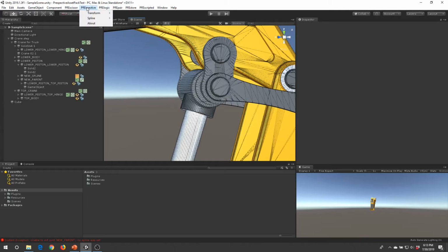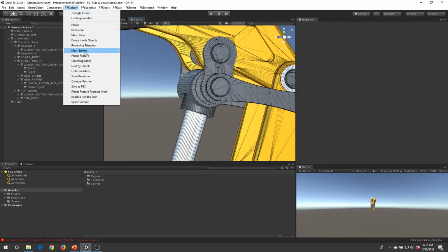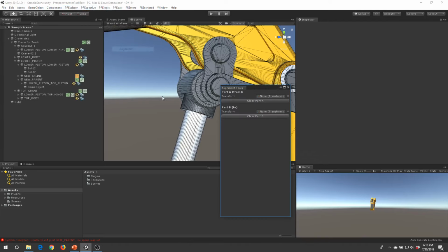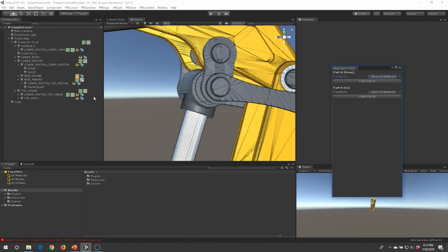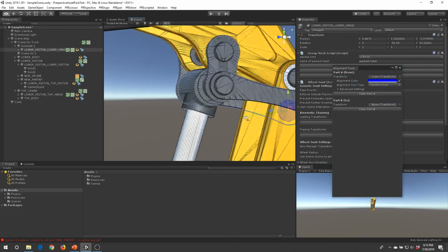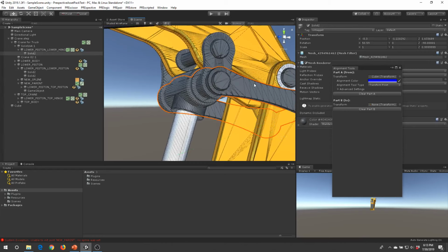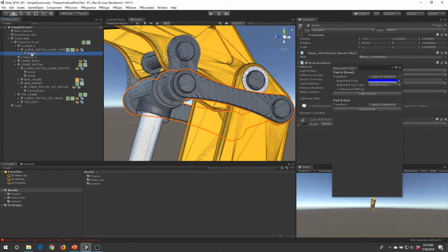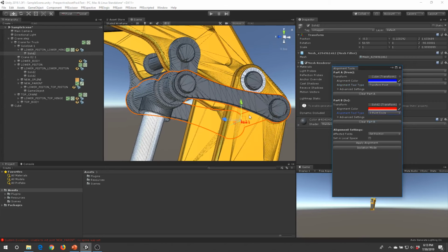So we'll go to prepare alignment, select the cube again because we're doing that anyway, transform pivot, and let's select this particular part. No, that one. Yeah, so we need a solid. Let's add it in there, and let's say 3-point circle.